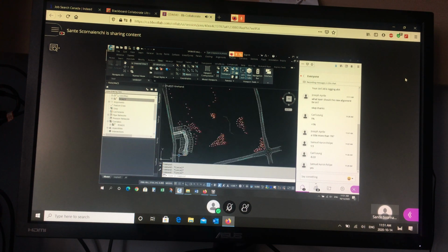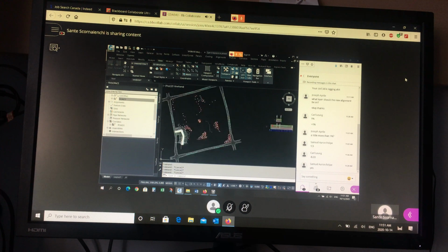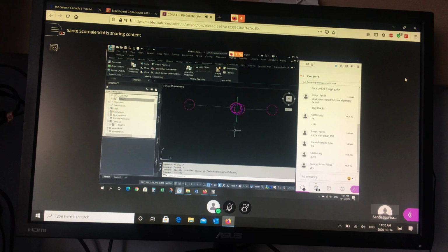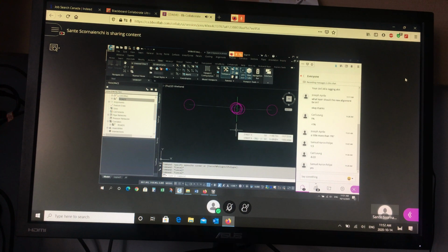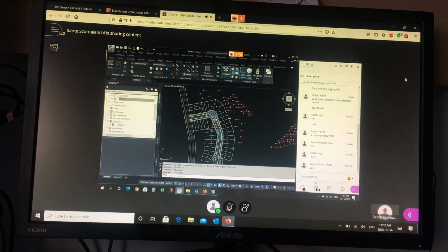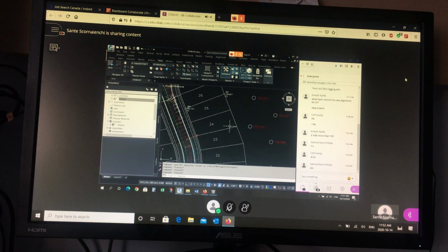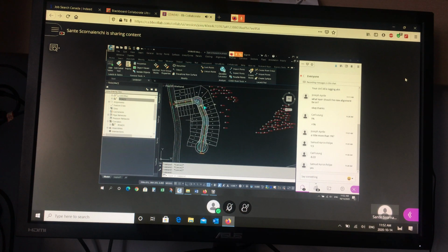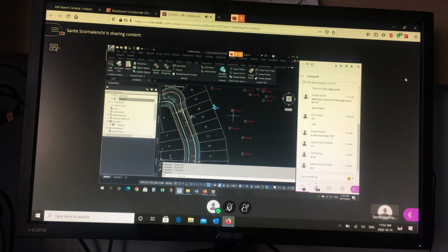Okay? And I suggest you try and reuse this one. Make sure that your horizontal alignment goes around so that the boulevard's always on the same side as the elbow. Okay? I'll talk more about that tomorrow. Next week. Okay? So once the corridor model is ready, at the end of assignment 3, when you hand it in, you're going to show me all the front lot corners in your entire subdivision and all the rear lot corners from your entire subdivision.